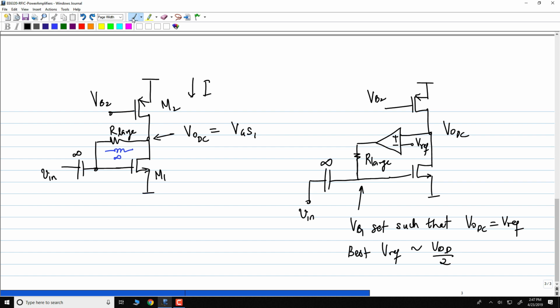So what happens is, right now the PMOS is being used only for bias. The NMOS is being used for the signal. Correct? But you can do biasing with both and signal with both also. So the next circuit should of course be something where, if you design the widths, I'm not going to go into the CMOS inverter here.